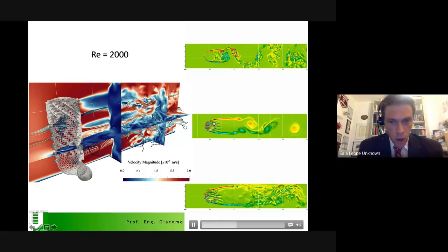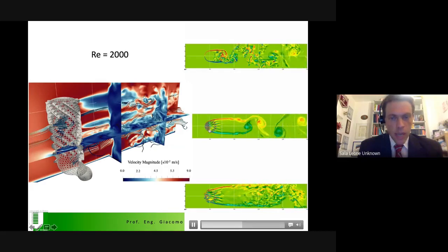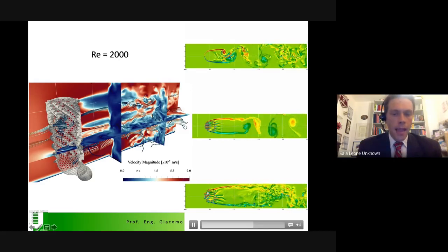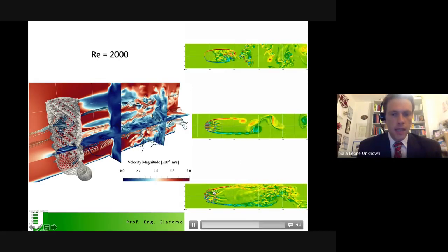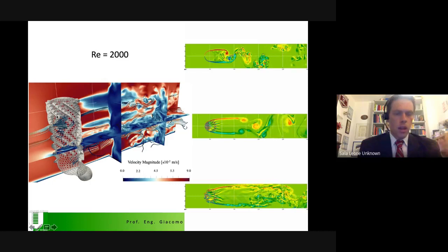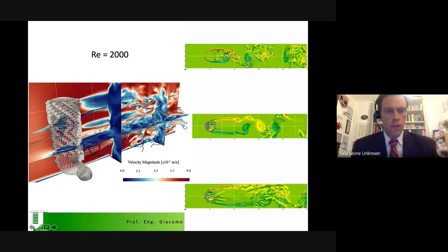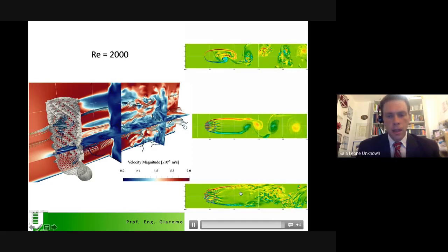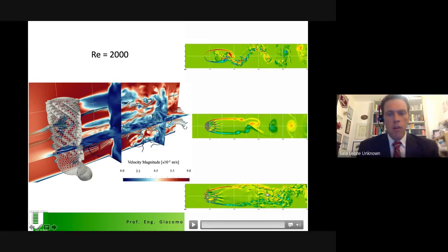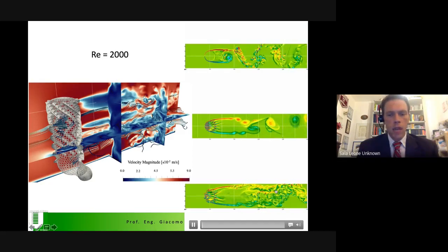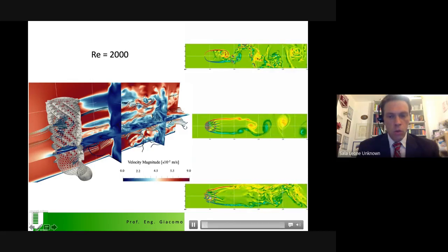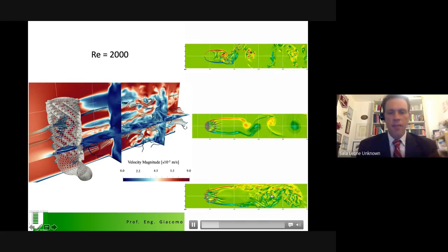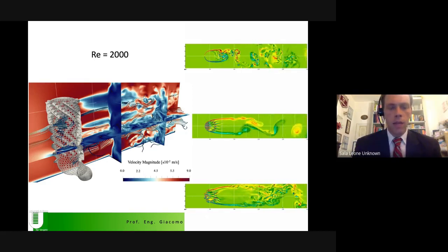The presence of the holes pushes away the vortex wake, and the presence of the ridges, which of course also have a structural role, keeps this mess of intermittency downstream of the structure, so the exoskeleton does not feel the intermittency that is felt 5 or 6 diameters downstream.